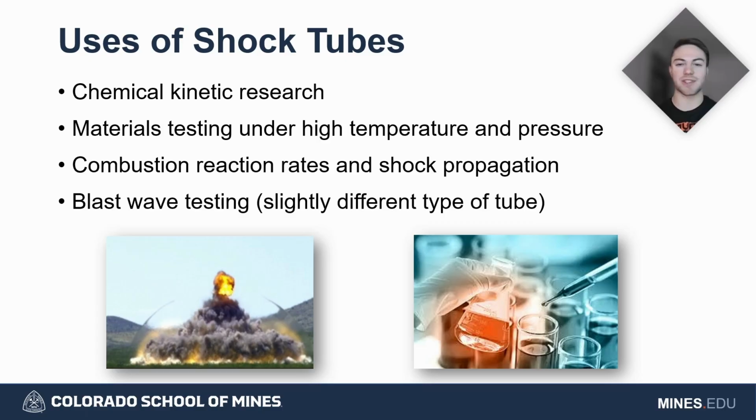You can material test some systems. So if you have a diaphragm material or just anything you want to test in an explosive environment, you can put that in between the driven section and the detonation section, and it will then tell you, hey, does this material break? Where does it yield? How does it yield? And can give you a lot of good engineering data on that. You also can obviously figure out some combustion reaction rates, as the rate is specifically tied to your speed and your movement of energy within the shock tube.